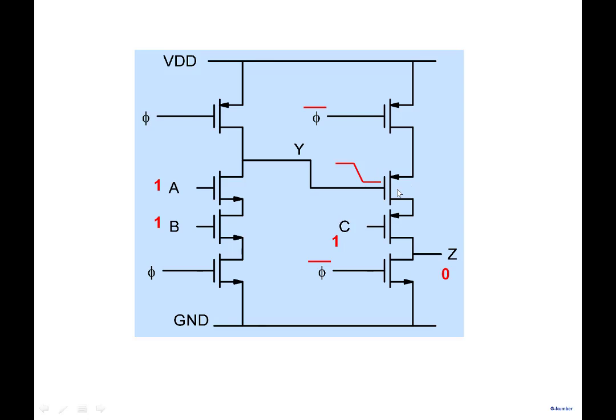So there's no error. The error occurs only when the incorrect logic, when you pre-charge, is wrong. It's pre-charging a node to VDD, but I don't know whether VDD or ground is the right value. If VDD is wrong, then the wrong value should not propagate. It should not turn a transistor on and cause an error. So in this case, when you turn it on high, a high value doesn't do anything to the PMOS, which remains off. So no error occurs at this particular point.